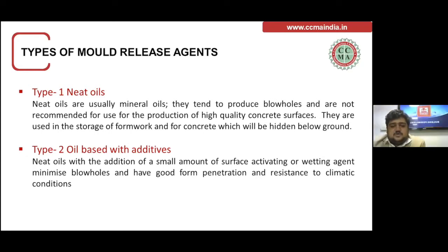The second type is oil-based with additives. So oil-based with additives has wetting agents to minimize blowholes in concrete, and they are good for penetration and to resist chemical and climate conditions. So this can be used while it's raining, or when the surfaces are wet, or the plates are washed regularly. So these are the oil-based additives which can be used for getting good fair-faced concrete.